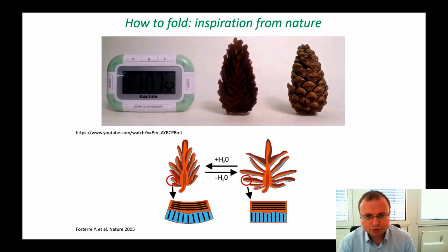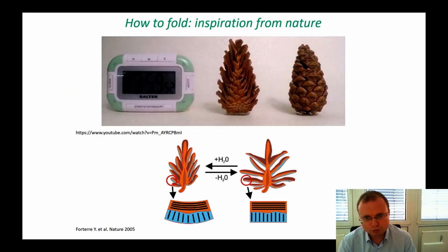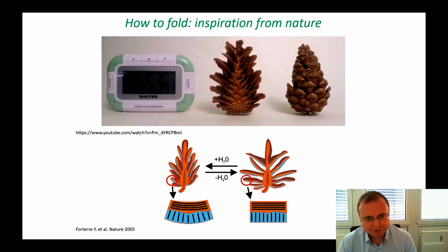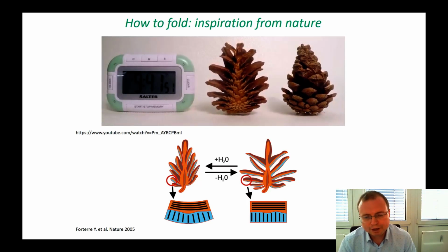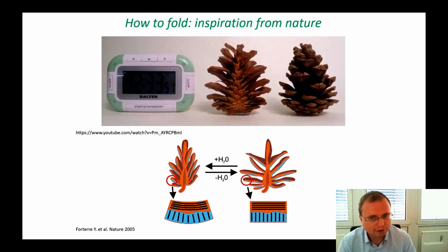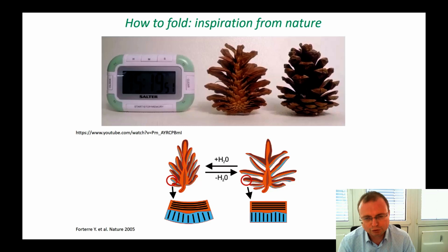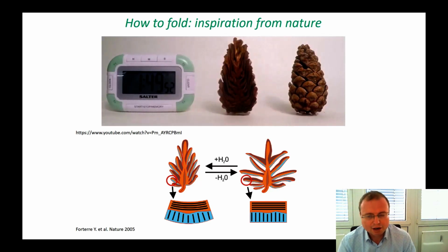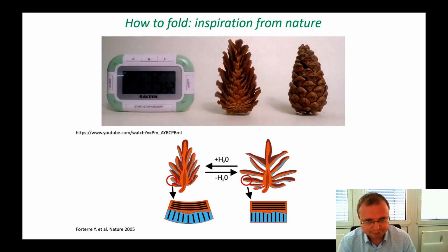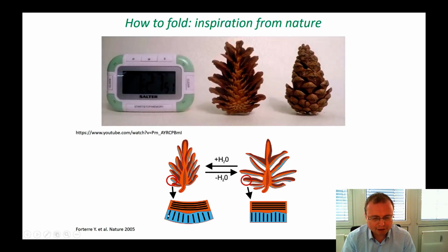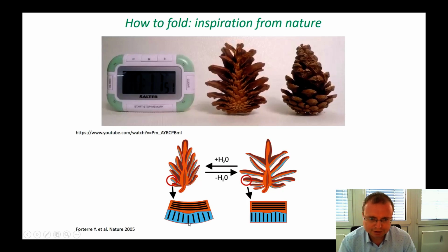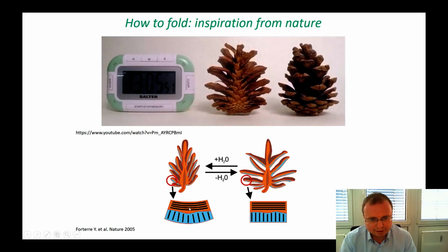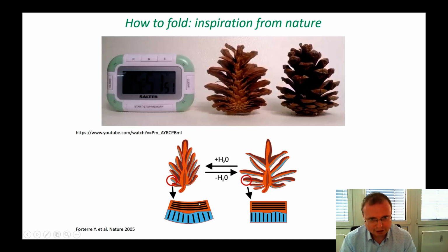One possibility is to again look around and to find inspiration in nature. Most of you have seen pine cones, and most of you paid attention that pine cones are closed in summer when humidity is high, and they open in fall when humidity falls. The pine cone uses this mechanism of opening for dissemination of the seeds. The most important for us is to understand why it happens. Pine cones have a bilayer structure with different orientation of cellulose fibers. The cellulose fibers do not extend upon the swelling, but only the distance between them can change.